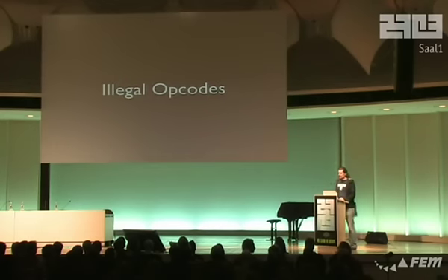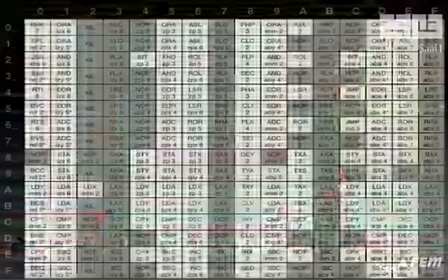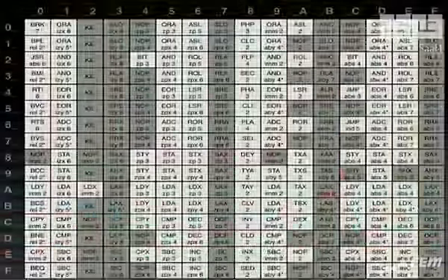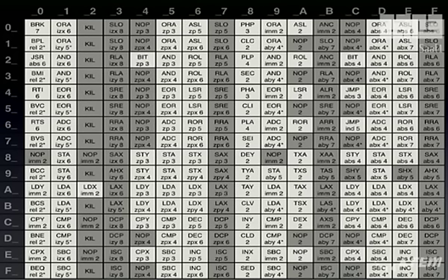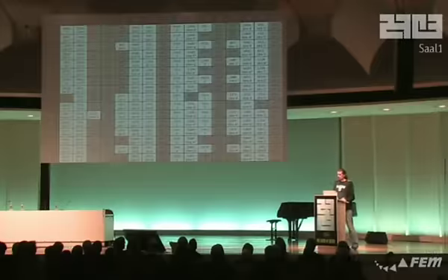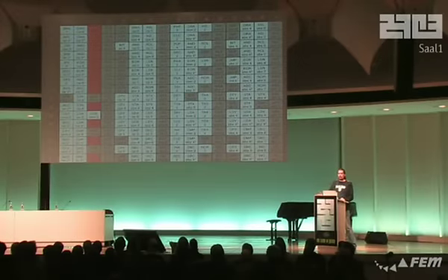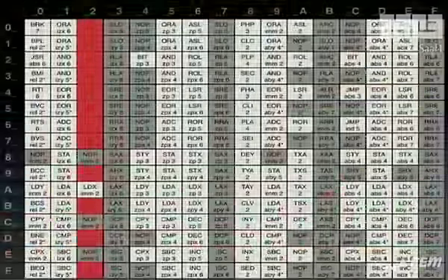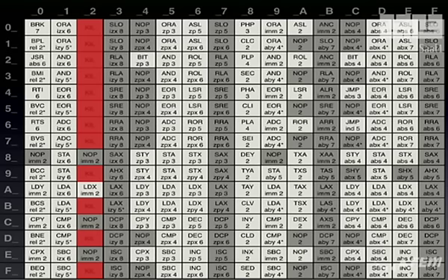So now this is illegal opcodes. These are the holy grail of understanding the 6502, and I think we have made some progress there. What people have done so far is mostly measure them and see what they are doing. And there were some theories that they seem to combine the ones that are close to them, but now we can say a lot more about them. So the kill opcode, for example, all these, most of them that end in 2, they just halt the machine. Reset still works, but IRQs and NMIs won't get delivered.